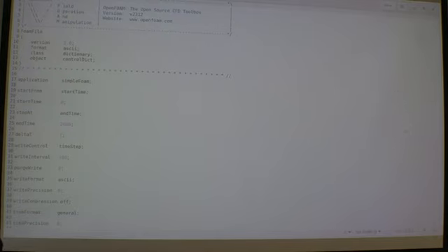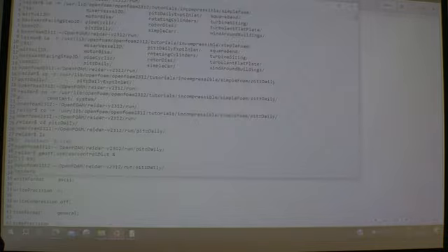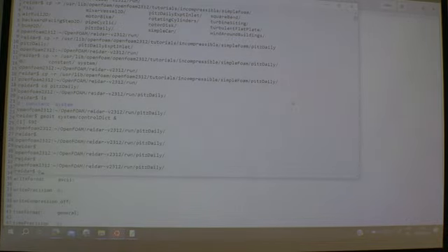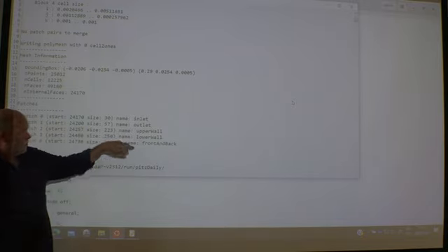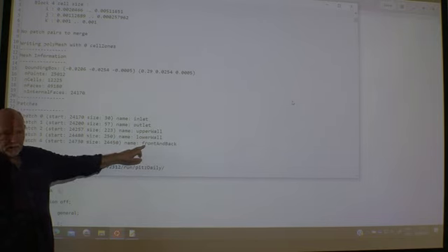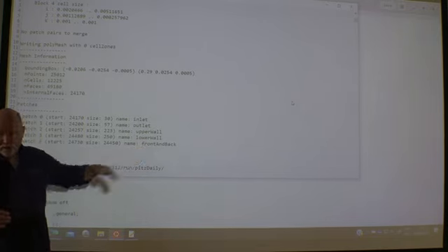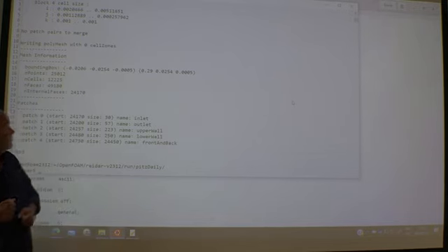Okay, let's just try to do this quickly. We have a blockMesh. And no errors here. We have an inlet and outlet, upper wall, lower wall, and we have front and back. As also a hint, front and back, it's a 2D case.